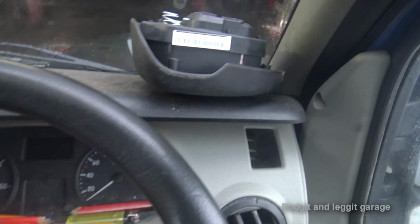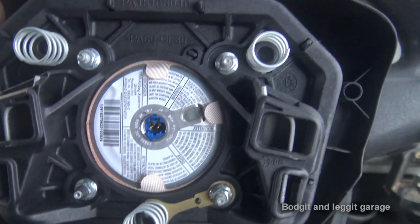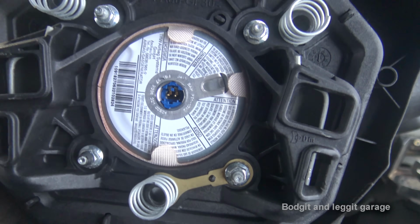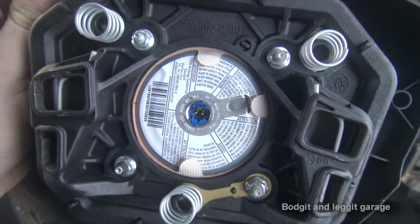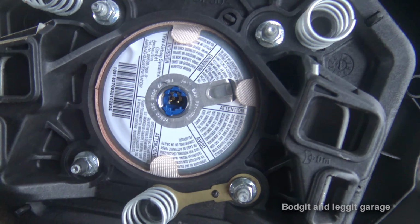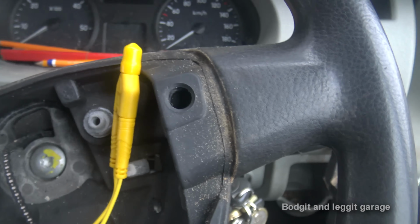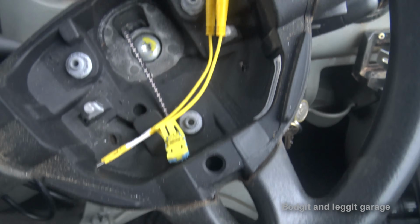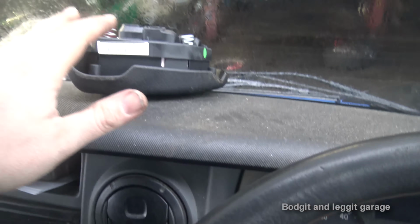Now, I have done a video on how to test an airbag, and a lot of people said, oh, you can't do it that way. And I proved you can do it that way because I'm still here. The airbag didn't blow up, so there you go. But if you are afraid of going directly to the airbag, what you can do, so we know we've got a problem with our driver's airbag, we've now disconnected our airbag. Just imagine that as a big resistor. That's all you've got to imagine it as.